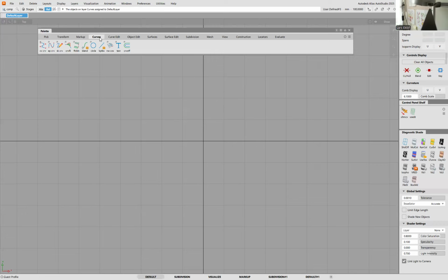So I'm going to click out a curve here by using new CV curve and just make sure that I end up somewhere around here with my curve. And I just click out four CV points